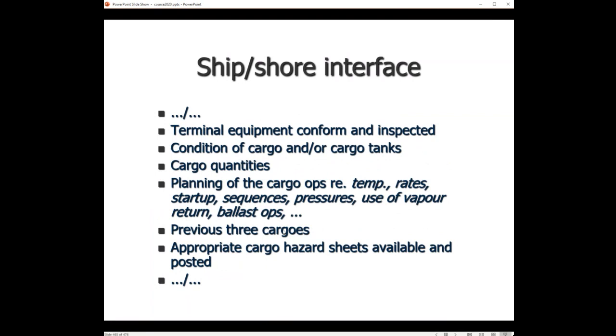Terminal equipment is confirmed. Condition of the cargo tanks. What is the actual temperature of the cargo? What is the actual pressure in the cargo tanks? What is the cargo quantity that you need to load or that you need to discharge? It's better to discuss this beforehand and not afterwards, because then it's too late, of course.